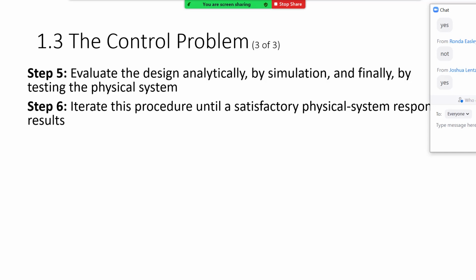And you will probably see it even in some of the problems that we will do. We'll design a controller thinking this should behave exactly somehow, and then when we try to implement it, we say, oh, it did not. It might have gotten us closer to what we want, but it did not do exactly what we want, because there is a zero here that we should account for, or there is a pole there that we approximated, or we considered its impact very, very small.